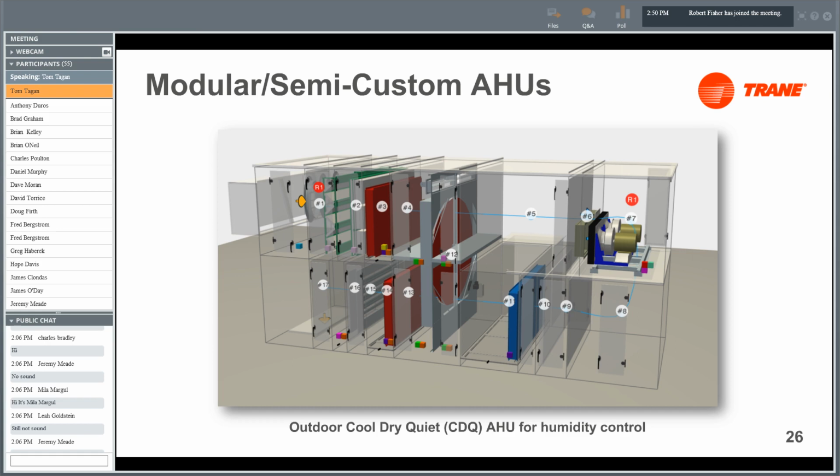for a manufacturing facility also in Acton, Massachusetts. So walking through this air handler, your outdoor air enters at the top, passes through your filters, your heating coil. This wheel here is called a CDQ, which stands for cool, dry, and quiet. The air gets to your supply fan, it makes a turn, it goes to the lower level, passes through your cooling coil, CDQ again, heating coil, humidification, and discharge.